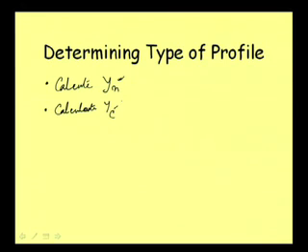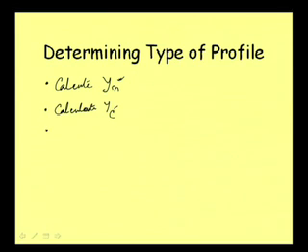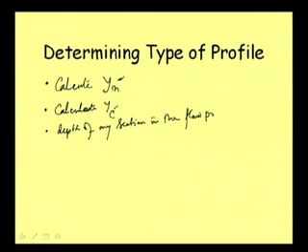And then based on the statement of the problem, or based on what we are observing in the field, or the situation we are expecting, suppose a dam is there, we know the dam height, or say a weir is there, we know the weir height. So the flow profile will have to cross that, meaning we must know the depth of the flow profile at any section. We must know the depth at a control section, and that may be the control section also.